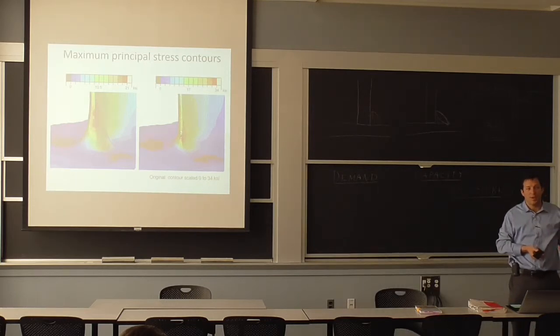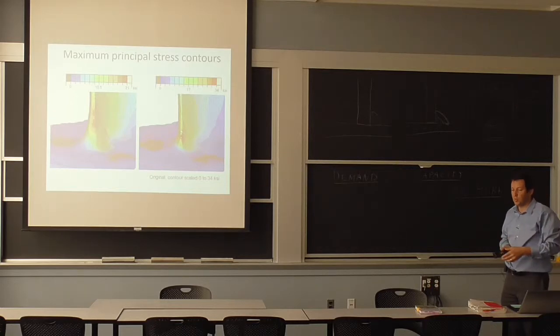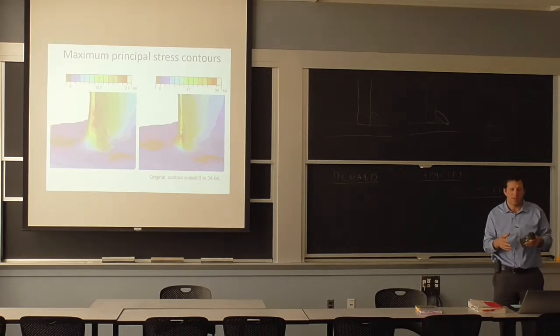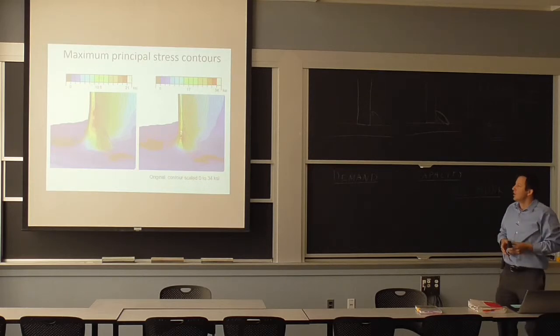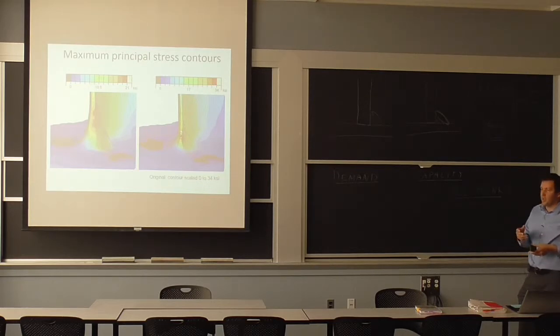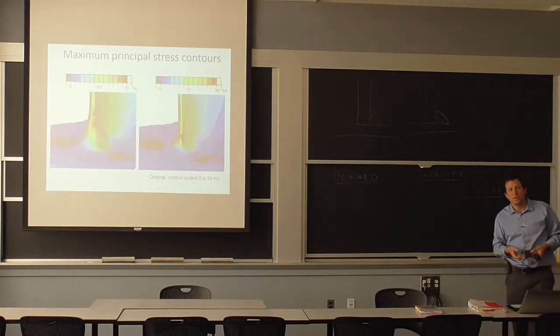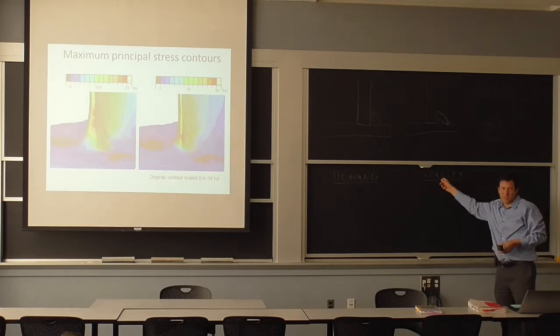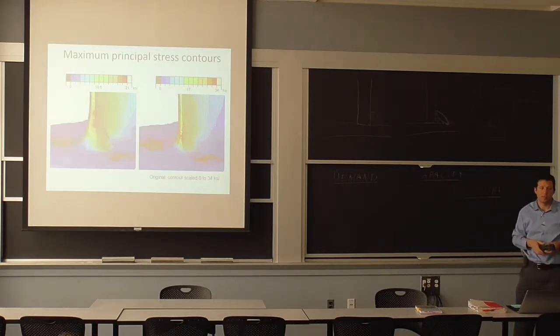That's great. If you use the same manufacturing process, I'll buy it, right? But if what you're going to do is now change the process from this very sophisticated casting to an additive manufacturing that will add residual stresses, will produce a different microstructure, is where all of a sudden my capacity is going way down. And therefore, you know, it didn't go with the FAA, and it makes sense.